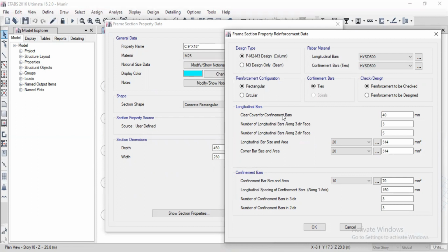You know what is the clear cover, yes or no? I think I know just the CC, which is concrete cover. Okay, concrete cover. So basically, clear cover is the distance between the outermost surface of the concrete and the reinforcement, from the bottom and the top, all around. For the column we put 40 mm cover, and for the beam we put 25 mm. Yes, for beam 25, column 40, for footing 50 mm.